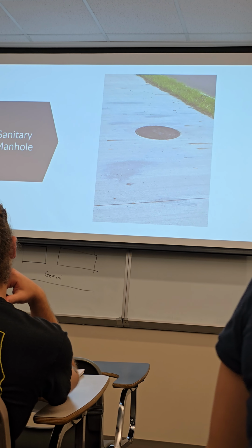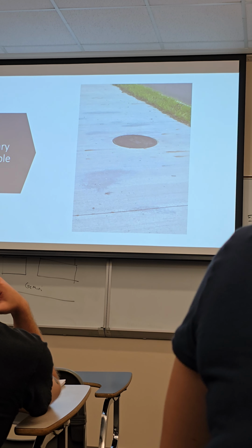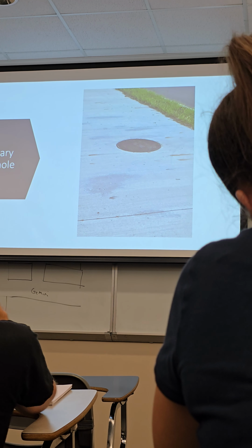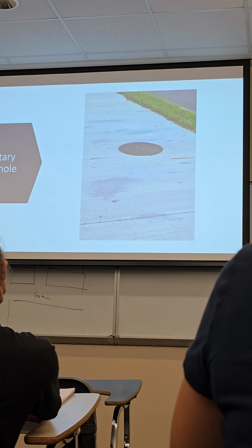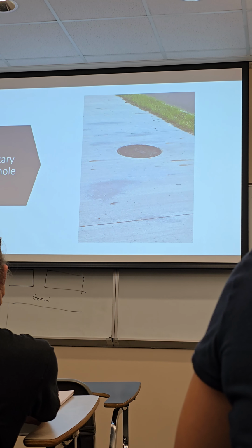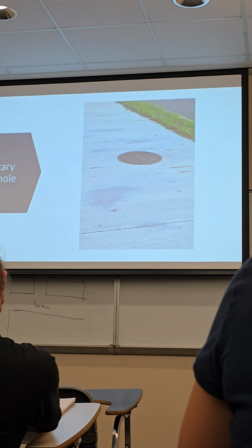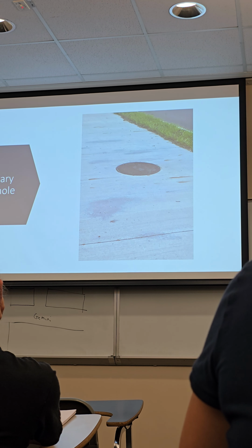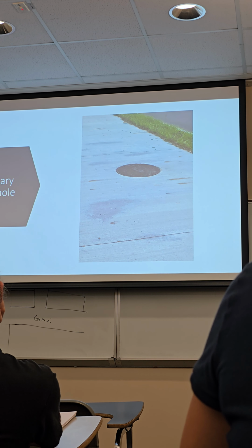Yep. So when you're designing the location of each manhole, are you trying to avoid the roads? Well, for a residential roadway, it's in the road. And I'll show you a typical section that kind of shows you where that is. Where you want to avoid it is in a road that has more cars.